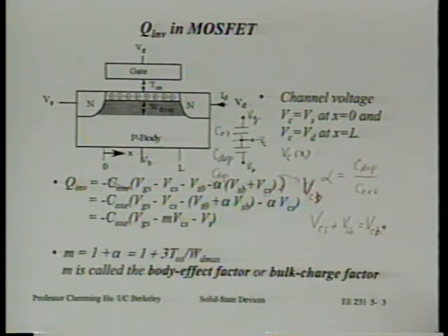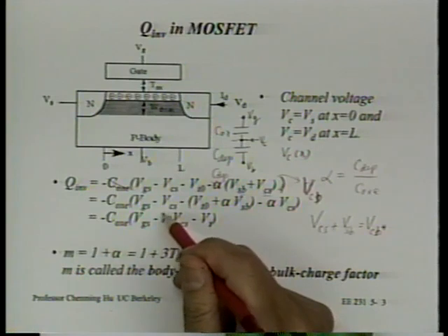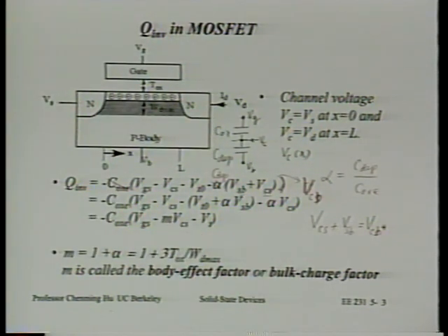Now you probably find this very familiar if I take this M away. This is VGS minus VC minus VT. So I would like to ask you to just carry this M. This is a more accurate model, which includes the backgate effect. And backgate is getting more and more important, and in fact has always been important. It's certainly very useful to keep backgate in mind from the beginning as we understand the MOS transistor.